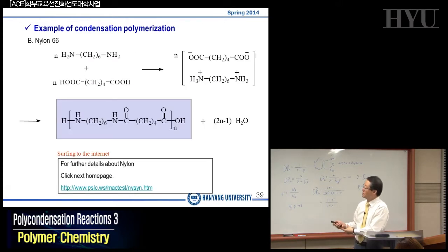Well, nylon 66 can be made by a two-step reaction. I think we have already talked about this. We have hexamethylene diamine reacting with adipic acid in the first step to become a salt. And in the second step, you remove the water by pulling a vacuum at high temperature so that the amidation reaction can occur. This is the aliphatic polyamide, okay, aliphatic polyamide, because we have the aliphatic linkages between the amide groups.